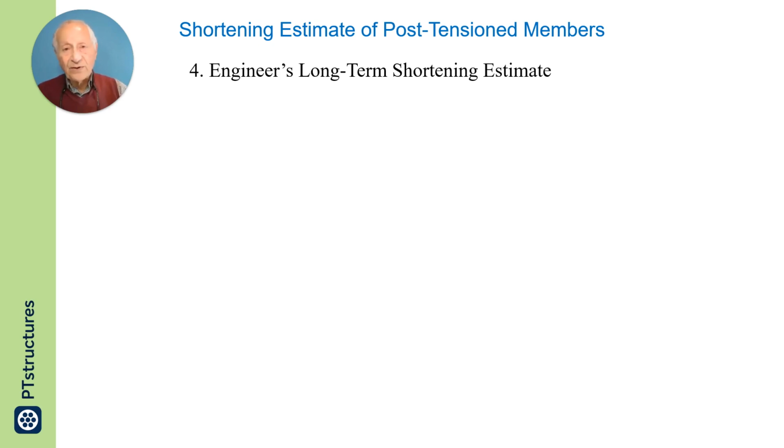Why do you need to know that? Because depending on the detail and the amount of post-tensioning that you may lose to the supporting members, you impact the safety, the bending capacity of the post-tensioned member. So you need a quick and rough estimate.